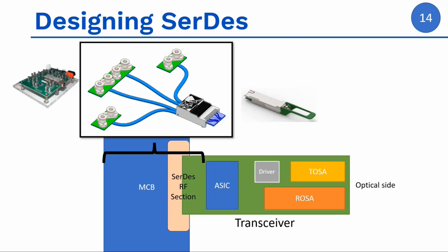But you have hundreds of them combined together in a TDM fashion, time domain multiplexing, to create one signal, and consequently this signal has a very high data rate, in gigabits. In our application now, we are talking about a 112 gigabit per second signal on each one of these lanes.